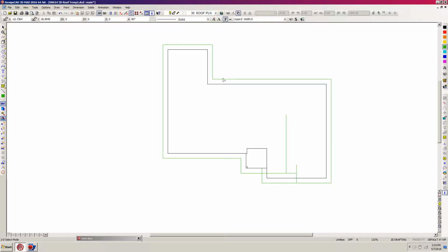And so I need to find my ridge for these two guys here. So I'm just going to hit V for vector and K here, and come over here somewhere and hit K, and hit enter, or hit my scroll button to initiate a command. Hit V for another line, hit Control K, and now I want H for orthogonal mode. I want a nice straight line coming all the way over to this guy, and hit K. And now I want to take this new ridge line and use the extend command and extend it on over past this other line, hit escape, get rid of my reference line, select it, hit delete, and trim this to this line now. E, right there, hit H to go out of orthogonal mode and click there. Okay, so that's my ridge, my primary ridge really.